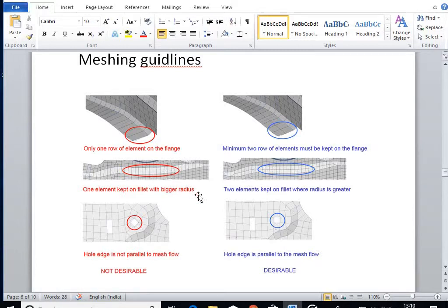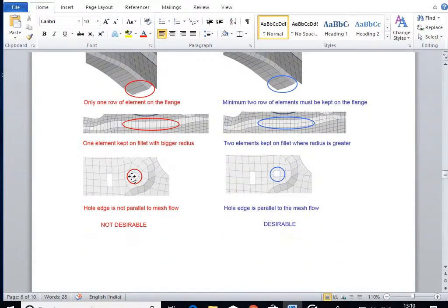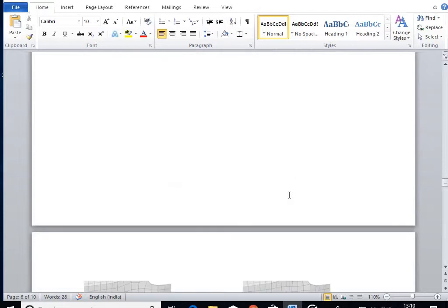If at all the element size is failing, then it is an exceptional case. And always try to make the slit with a washer. If the washer length is very minimal, then try to go with the even flow or in the direction of the element size itself. As you can see the two different values over here, I'm zooming it out. This is how you need to make it: instead of making it diagonal or perpendicular to the direction of the flow alignment, you make it parallel, right?